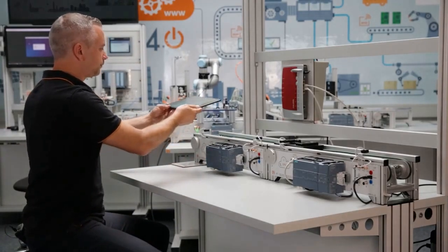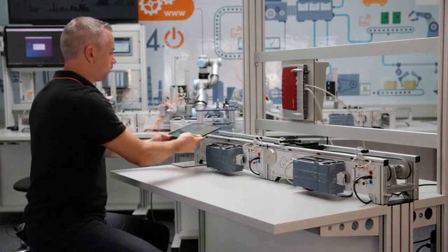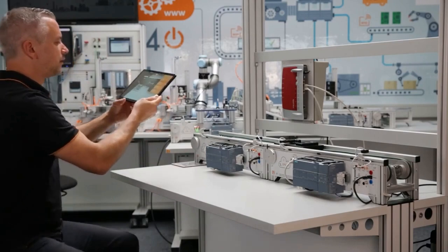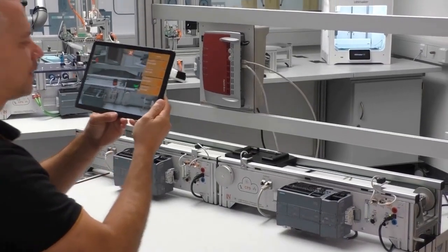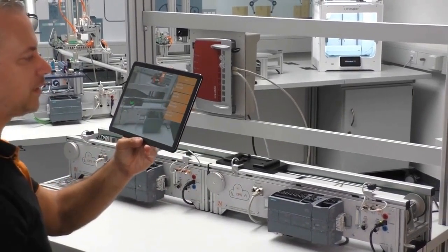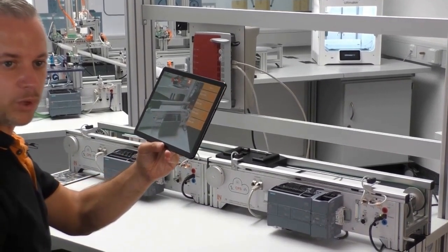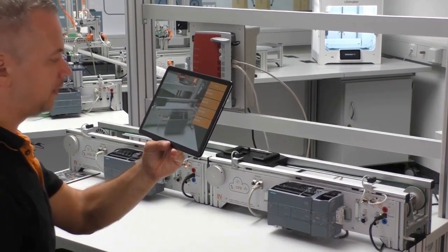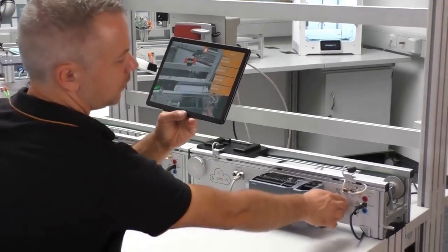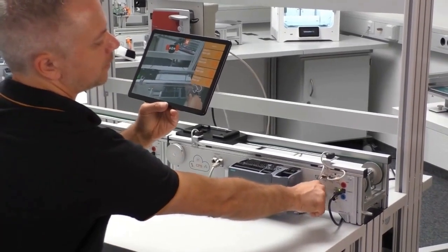Then I should briefly reload the anchor here again, and we get the signals displayed on site where we have configured them. But if I am here in the system now and there is an error somewhere in the first conveyor belt, I will simulate that by simply setting the sensor here.